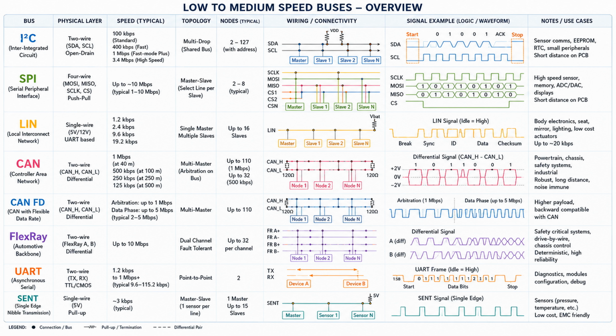Modern vehicles and embedded systems increasingly combine multiple buses simultaneously. For example, LIN handles low-cost actuators. CAN or CAN-FD handles control systems. FlexRay handles deterministic safety systems. Ethernet increasingly handles high-bandwidth ADAS and AI data. Rather than replacing one another, these buses form hierarchical communication architectures.